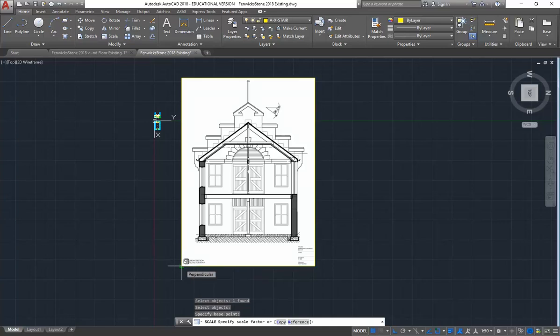And then the scale factor is simply the size we want it to be, which was 7820, divided by the size it is. When it asks for this, it'll say specify scale factor, and then you can just start typing. So 7820 / 153,400, which is 0.0510. That's the scale factor.